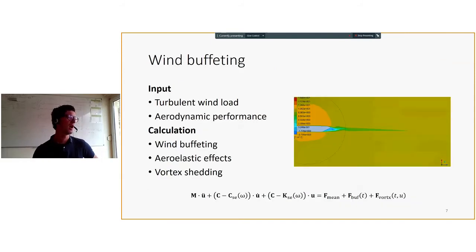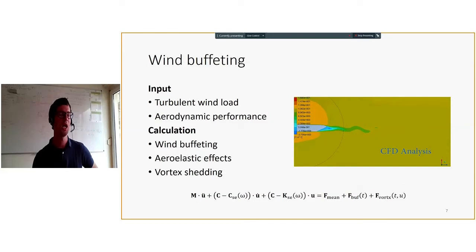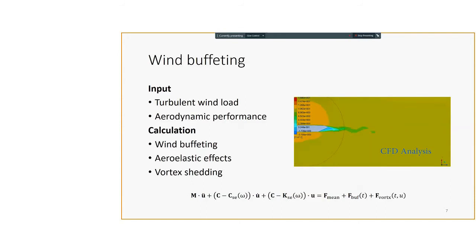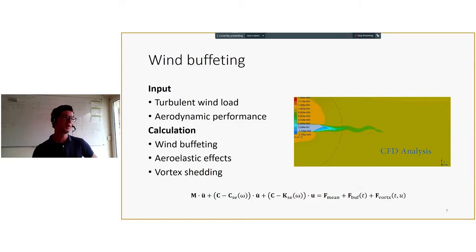We will be focusing today on the wind buffeting formulation. This has also been developed through my implementation in the software. We added a homogeneous, actually linear, wind field simulation, where we simulate the turbulent load on the bridge, and we also take into consideration the aerodynamic damping and stiffness.